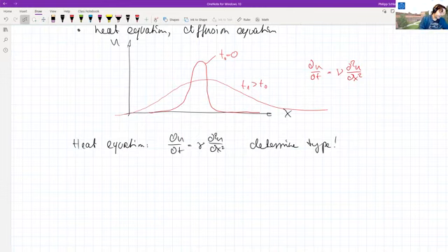But of course, we still need to be able to formally show it using the technique that we discussed yesterday. Now, if we want to do that, we again need to realize, as in the example of the Prandtl-Glauert equation yesterday, that we have a problem, namely that this is a second-order equation, but what we actually need is a first-order equation to use the method from yesterday. So we need to rewrite it as a first-order partial differential equation. And of course, we do the same trick.